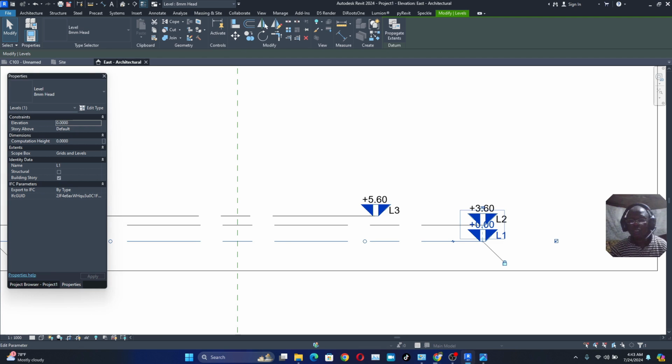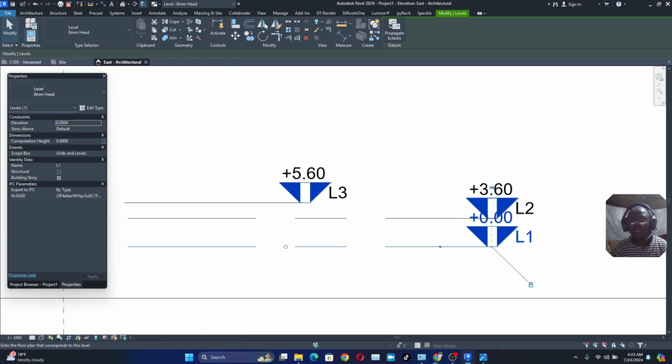We click on this, right, try to get this. This is what we want. Just click on this, then enter the 54. That's your base height, right? Just say 54 meter. That is where you are going to start your structure. Base will start from there and move upward. You cannot start from the 0 level, right?